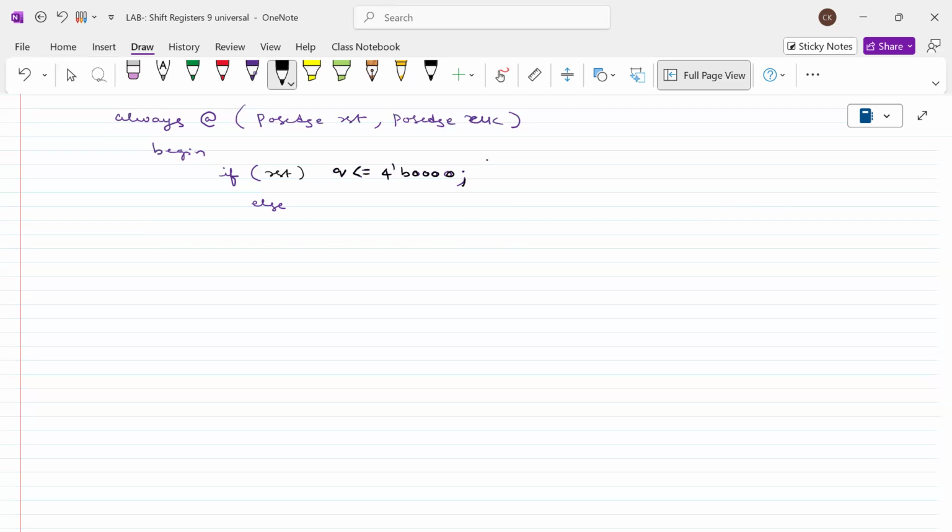Right. We have 4 options. Better we write many options; many procedural statements we can use. Case is the best choice. If you want, the ternary operator we can use, but the simplest one is the case statement. Okay. Case of selection line, right? We have to write the case. Case of selection line.